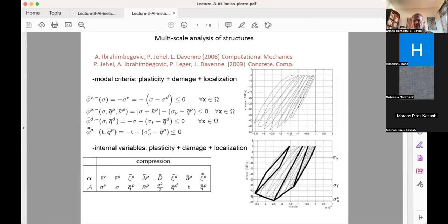You start basically here and you keep increasing the values. You can see at a certain point you will have a residual deformation, bigger and bigger as you go along. And you will also have a change of the elastic response as you go along. And then you go to the peak value of resistance and you go down to softening.